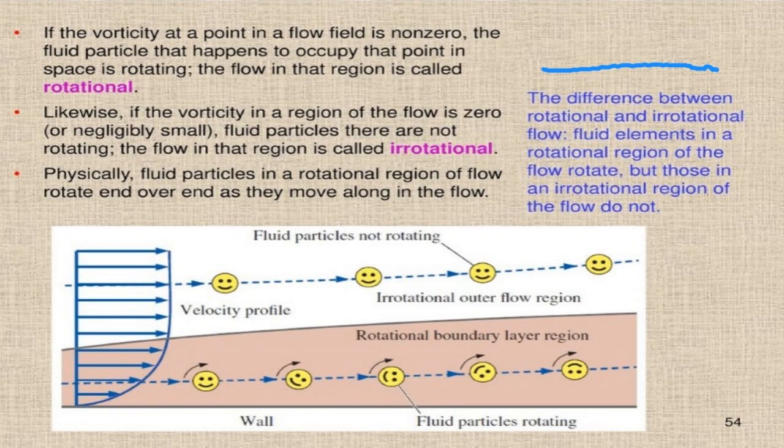So because of the viscosity, we have zero velocity here. Just above the plate, we have some velocity. Just a little bit above, we have more velocity. So it means that when you go away from the plate, your velocity starts from zero on the plate and increases to some point, which we call the boundary layer. We will see it later.